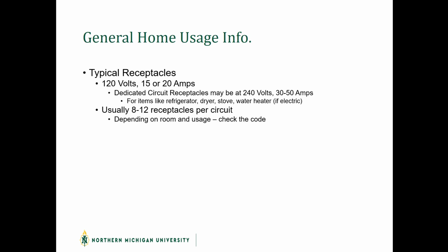And if we have a 100 amp panel that's coming into your house, with 20 amp circuits, you can only get 5 of those in your entire house. Well, you have more than 5 because the theory is you're not going to be plugging every single thing into every single outlet or using every single load on each circuit at one time. If you did that, you're blowing fuses or breakers.